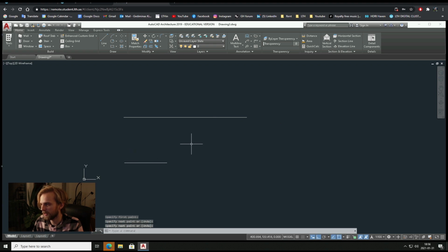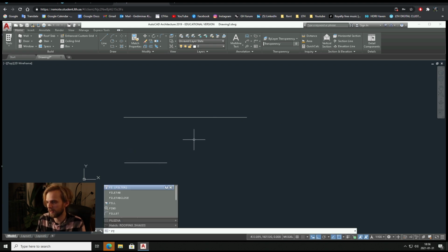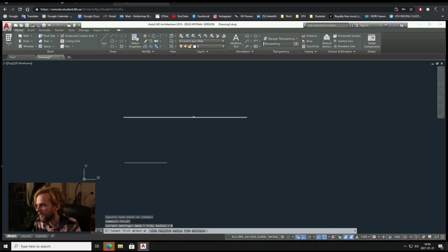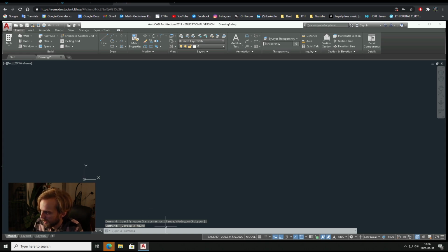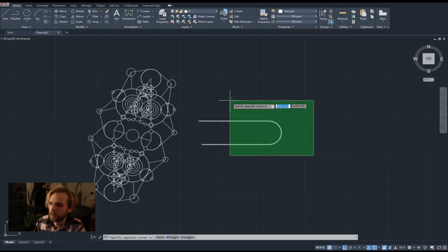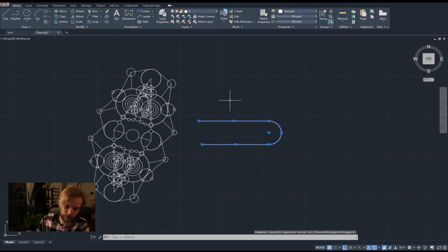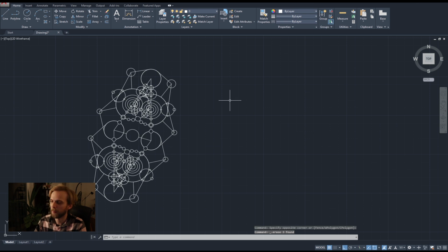One line segment, another line segment, fillet. Come on, fillet. Fillet from here, here. Yeah, it does work here as well. Cool. See, I'm learning something new as well. So if you have two parallel line segments, apparently it's going to just create an arc between them with a fillet, even if you say you don't want any radius for the fillet to have.